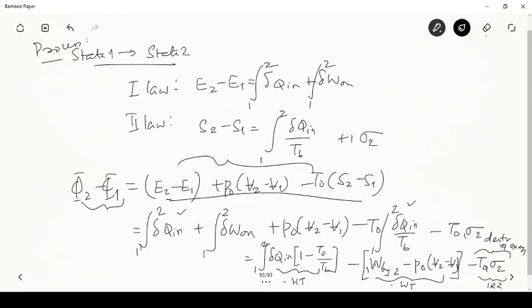So minus of that will be positive, and therefore it will move closer. But if there is a work on, then the object moves closer to the dead state, and if the work is done by, then it moves away from the dead state. Okay, and this one always destroys exergy, and therefore decreases the available potential to do work.